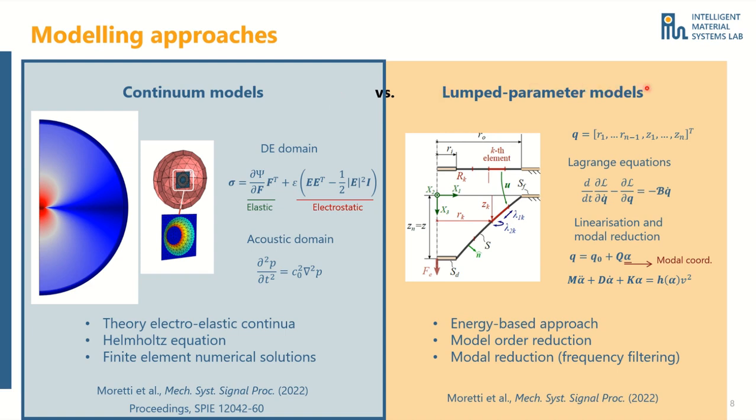We have also developed lumped parameter models for voltage-driven vibrations in DE membranes. And if you're interested, I invite you to have a look at our paper in Mechanical Systems and Signal Processing. Just to give you an idea, what we do there is to use a coarse discretization of the DE surface, write the equations of motion with an energy-based approach, and then describe the kinematics as a superposition of just a few of the mode shapes so as to reduce the dimension of the problem.